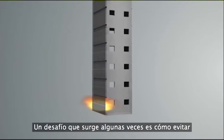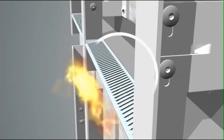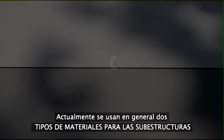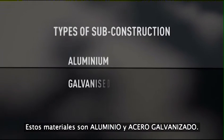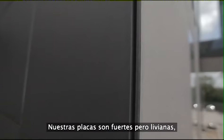One challenge that arises from time to time is how to prevent the passage of fire in the cavity. Promat's ventilated cavity barrier remains open until a fire causes it to seal up. Today, 3 types of subconstruction material are commonly used to carry our panels: These are aluminium, galvanized steel, or timber battens.